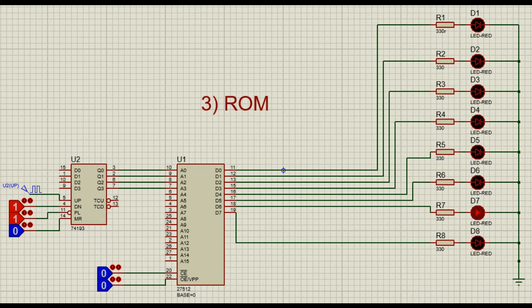Moving to the right of the IC, we have the Q0, Q1, Q2, and Q3. These are our output data lines, and the Q0 being the most significant bit. Below these, we have our terminal count up and terminal count down. These signal when the chip has either reached its max count or min count state. It is also worth noting that these are active lows.